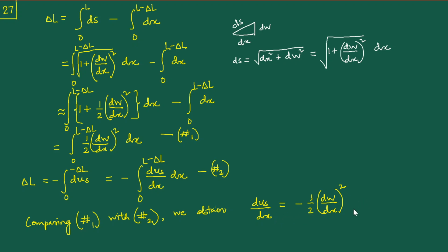Okay, so hence justified. And this entire justification is based on the fact that we are dealing with the shortening of the beam. So this is what is basically capturing that shortening of the beam. Okay, and this is the whole basis for this alternative formulation. So going ahead, we'll see how this alternative formulation and this insight into the shortening of the beam will help us to formulate a theory which will be more exact compared to the previous buckling theory that we have developed.